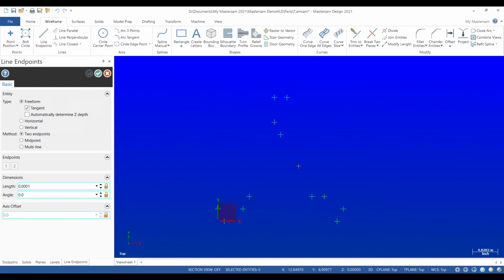This is a good opportunity to show analyze, actually. So we're going to right click and go down the list to the very bottom. It says analyze entity properties, and now we can figure out which ones are which. So I'm going to click this point. I'm certain that this is, okay, this is 0 and 2.